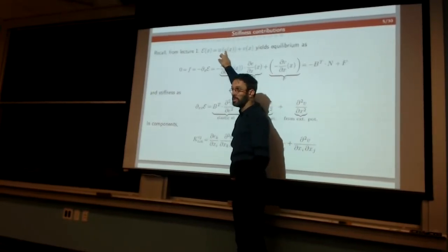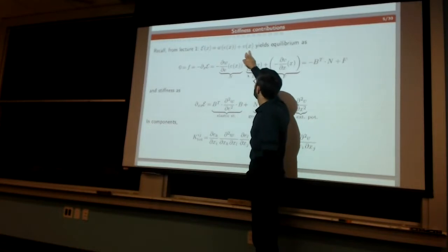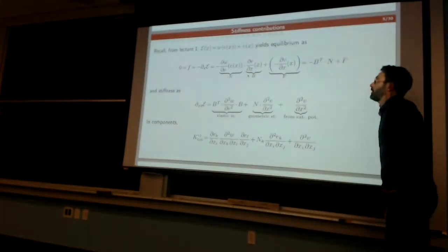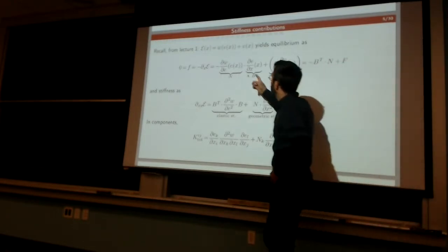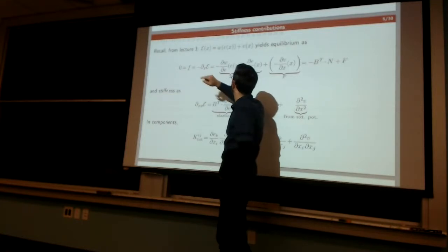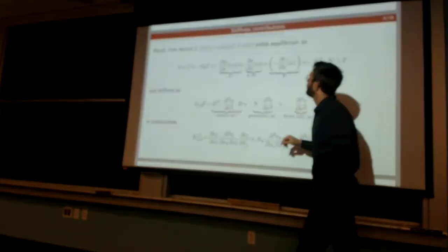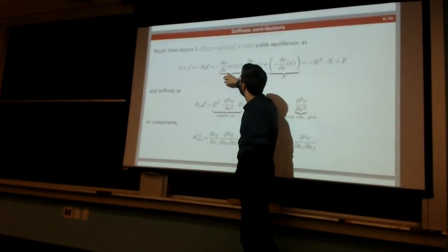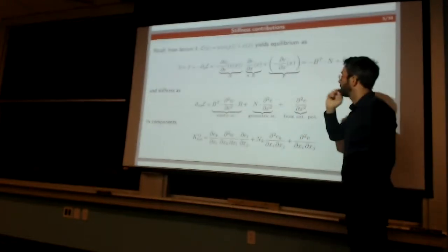And in terms of the strains, you define the internal elastic energy. And there's an external part that can handle any type of line load. You might remember that if we do the first variation of this to get the residual forces, so actually minus the first variation, there's a function composition, and you would find this guy, which is the internal stress, and this guy, which is the gradient of strain. It's geometric.